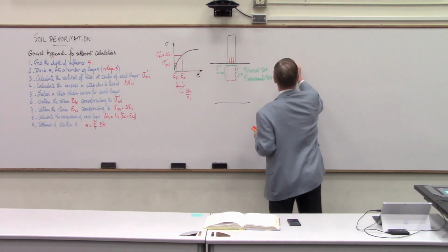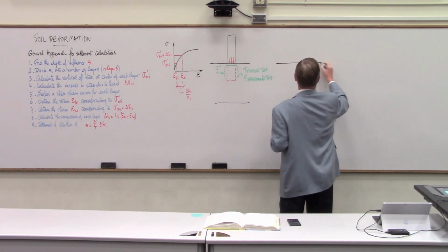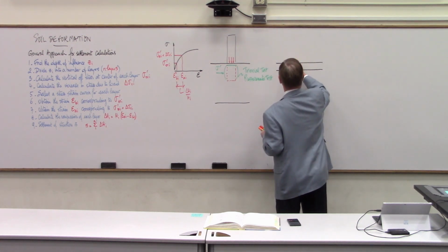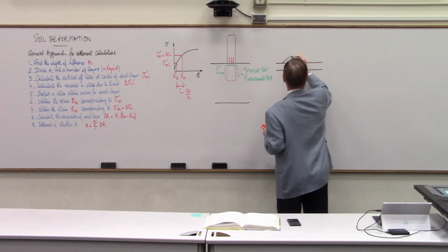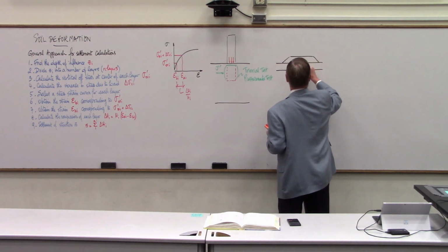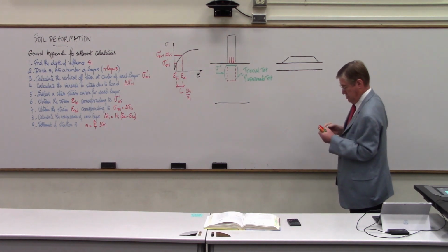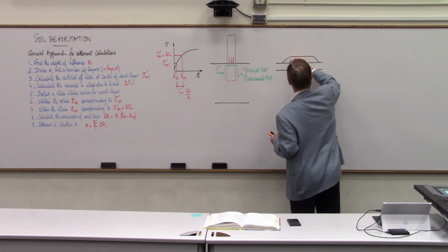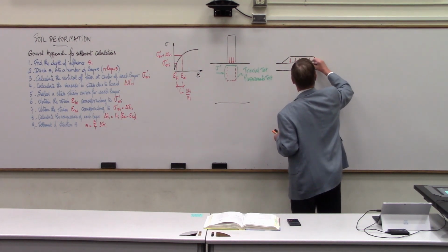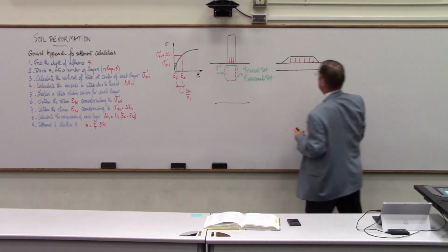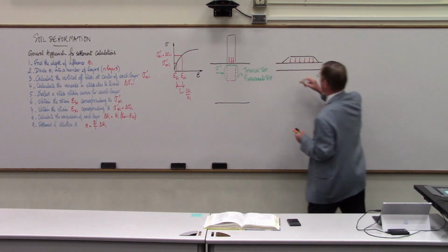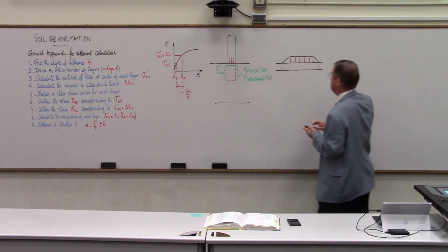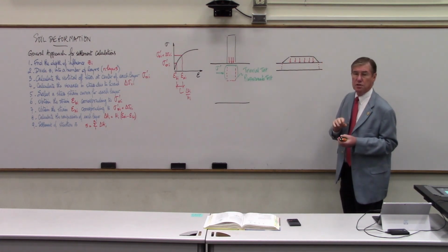If, on the other hand, you're dealing with a fairly thin layer of compressible material under a fairly wide loading, like an embankment, then in this case, so you have the pressure being applied on the soil, you can see that the zone of soil that you're looking at looks more like a consolidation test.